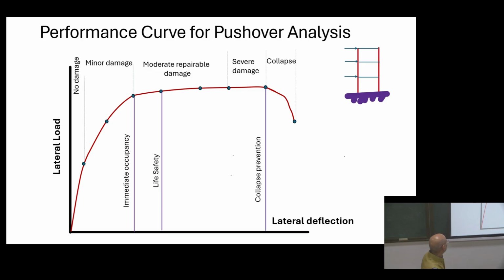So no damage in this one. When it is linear elastic, that means if you remove the load, it is going to come back to this level. So no permanent deformation is left in the structure. Then there is a start of something here: that is the proportional limit, elastic limit, yield limit, and ultimate, that is what you talk about.